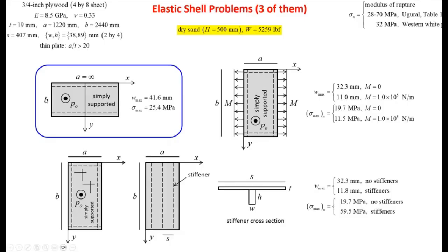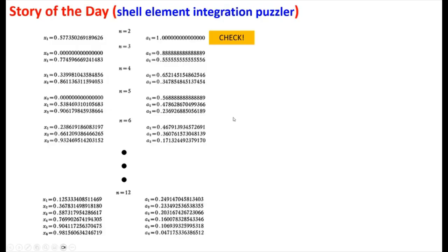So we go here. This is an analytical solution, simply supported plate with a pressure load. And we know the maximum deflection. We have an analytical expression, so we have it to all digits, right? So I run this problem, and I run it with a stiffness matrix solution, and I get an answer for the deflection, 2.6457938 millimeters.